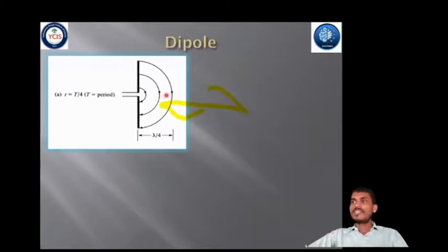This displays the lines of force created between the arms of the small center-fed dipole in the first quarter of the period, during which time the charge has reached its maximum value, and it assumes a sinusoidal time variation. The lines have traveled outwardly a radial distance lambda by 4. For this example, let us assume that the number of lines formed is 3.